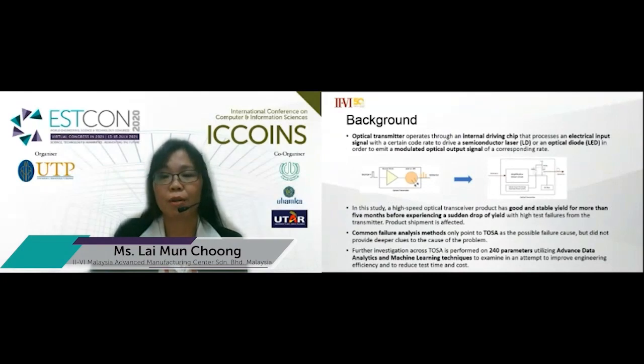As a background, the optical transmitter operates with an internal driving chip that processes an electrical input signal with a certain code rate to drive a semiconductor laser or an optical diode in order to emit a modulated optical output signal of a corresponding rate.